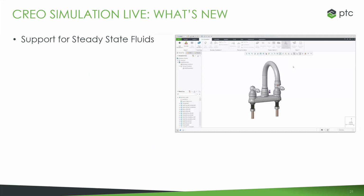And now with Creo 8, we should take a step back and say with Creo 7, a lot of the development time in the flow analysis was for transient studies, where the results refine over the course of time. And that's something that we wanted to introduce initially. But we also know that a lot of users want to design for the steady state. So with Creo 8, that's what we added, the ability to perform these types of steady state simulations from within Creo Simulation Live. So this will actually be the default now, and the user has the ability to switch between a transient state if they'd like to, over to a steady state, but now you have the option to move between those as well.